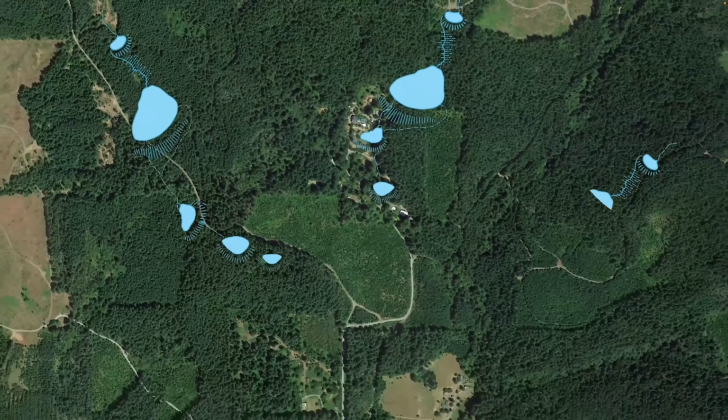The final element to consider is the outlet pipe. You'll want an outlet pipe if you're using this water for any irrigation use. It's important for aquaculture and fish culture, and it is also important for draining and servicing the pond. Oftentimes, people will build the outlet pipe right through the center of the dam. In that case, the most important thing is that this pipe is made of long-lasting material. I would recommend just using a good PVC.